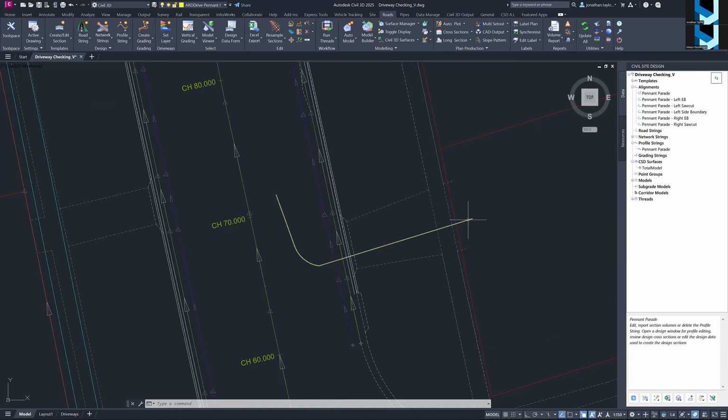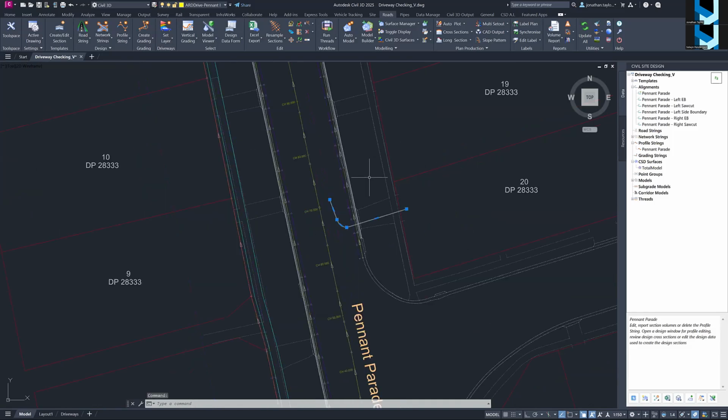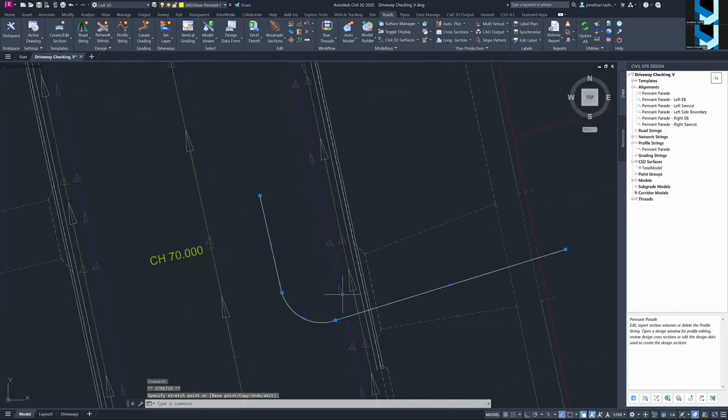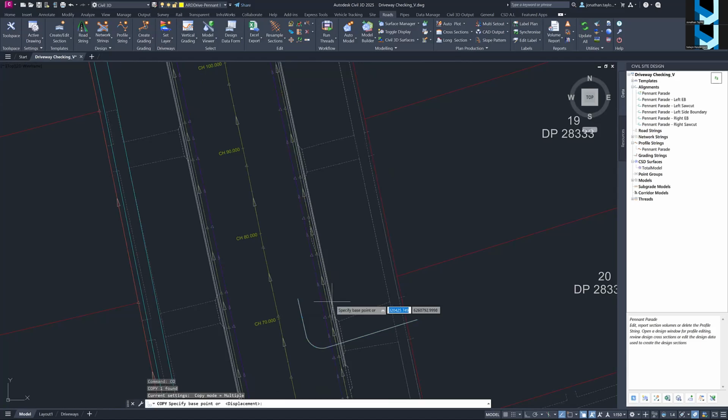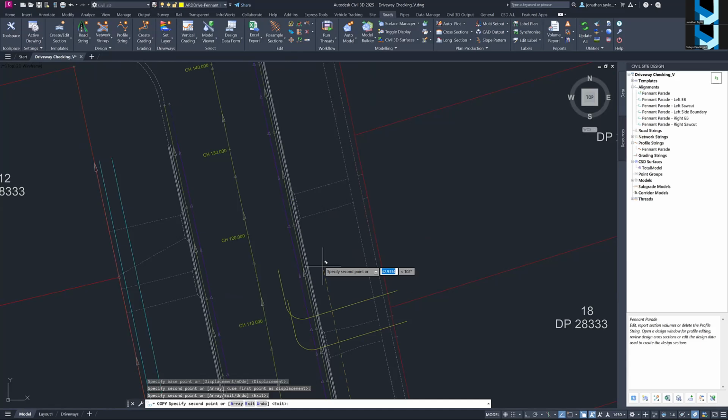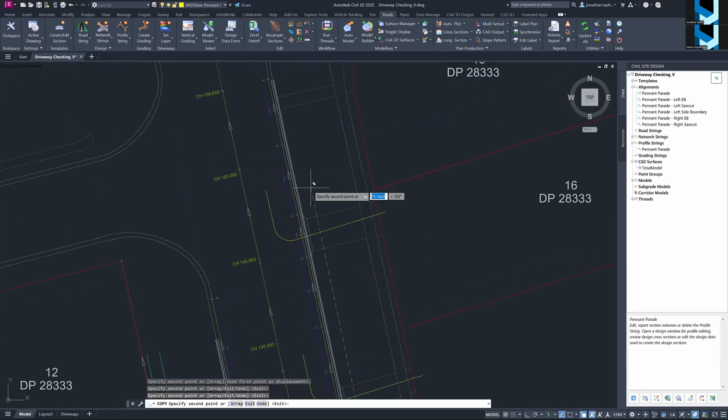Then what you also want to do is make sure the end of your polyline crosses over the point where the end of the check should finish. So in this case, it's that location there. I'm going past it to make sure that I get the end spot. The other great thing with this is that if you draw this polyline in a way where, okay, so that check might want to come over from this side. I actually kind of like the way that I've drawn it, such as this way here. You can just go ahead and copy this multiple times. Okay, it's just a polyline, and there we go.